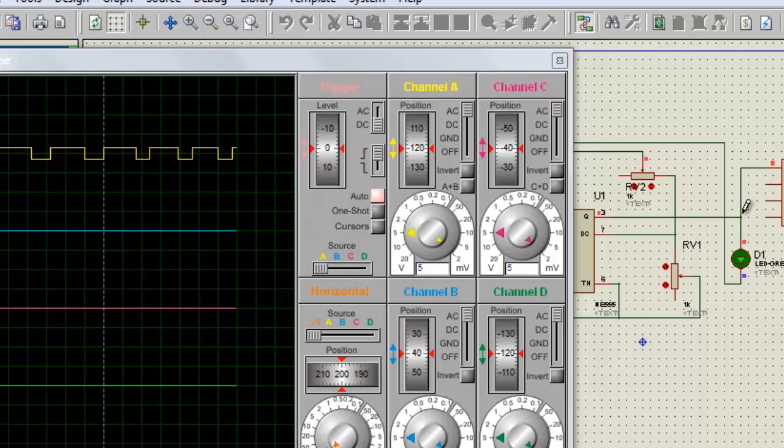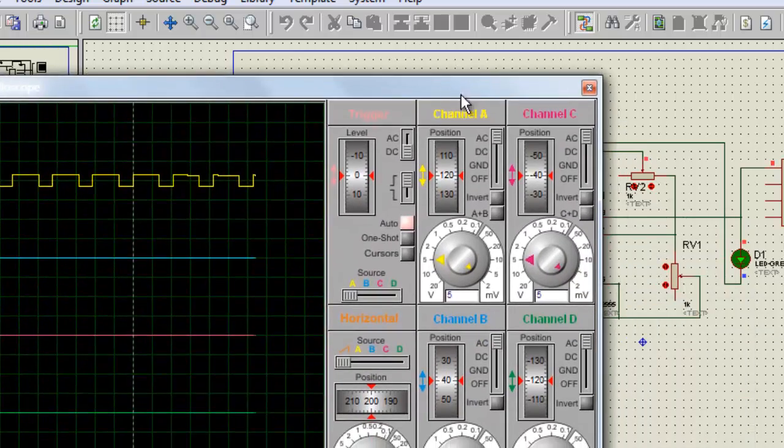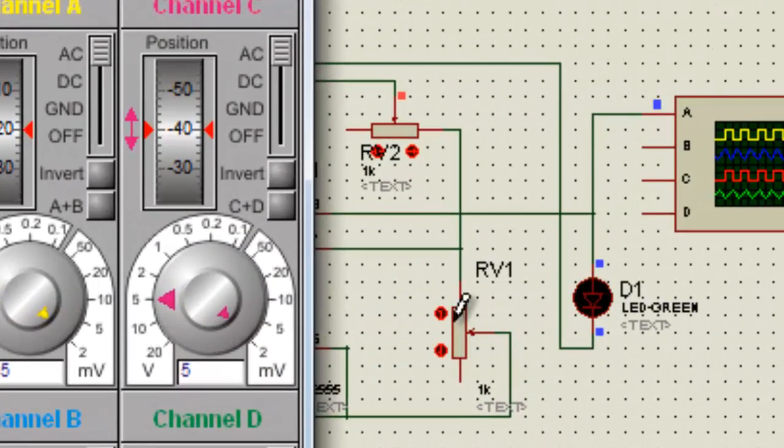So this is how you can provide various frequencies through this output to any kind of IC that works on clock frequency. And I've used variable resistors over here. These can also work as a potentiometer, obviously, because when you connect them to the ground part or something like that, they work as a potentiometer. But right now, I'm making them work as a variable resistor. So on increasing the pointer position, I'm increasing the resistance of this track, and similarly for this one.